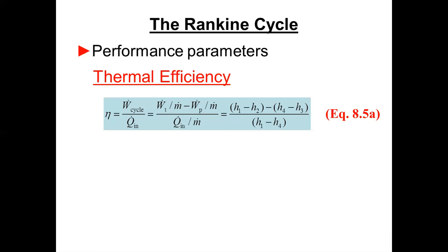And so in this case, for the simple cycle, all those mass flow rates are the same, and so all the m dots cancel, and then we can just plug in the enthalpy differences. By definition, it's the specific work of each and the specific heat input. So we just put in the enthalpy differences, and we get the equation for the thermal efficiency.